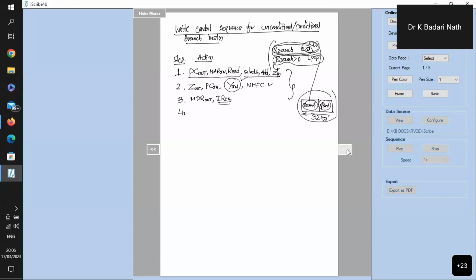So now I am extracting only that field of the instruction register. What is present as a part of the instruction, I am extracting that portion. I am calling that the offset field, of IR out. The instruction register contains the new instruction that was written into it. We know the instruction contains an offset. We are taking that offset value and it is output from the instruction register.